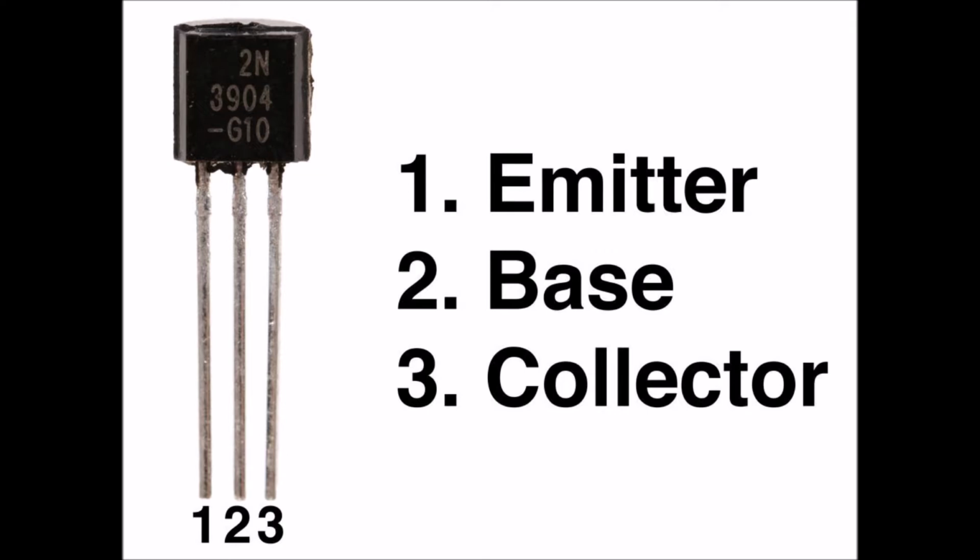We define the alpha cutoff frequency of a bipolar transistor, symbolized as Fa, as the frequency at which alpha decreases to 0.707 times its value at 1 kilohertz. Don't confuse this use of the term cutoff with the state of cutoff that we get when we zero bias or reverse bias a transistor under no signal conditions!